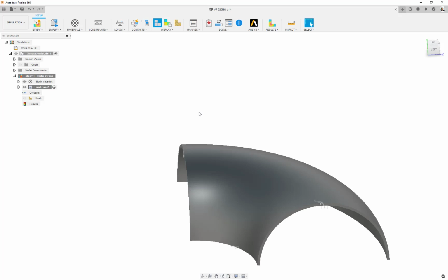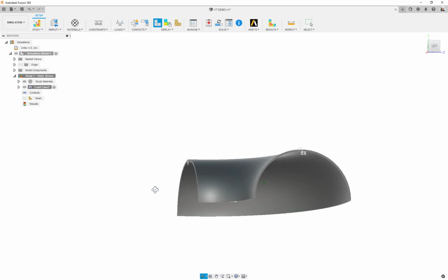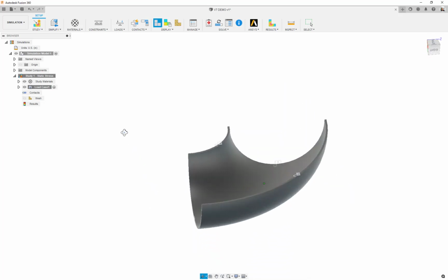And now this model is, because it's a single body, and at different locations on the model, I've accounted for basically all 3 translational degrees of freedom. So it's really kind of a neat thing. I know I keep harping on it, but basically, we're going to apply internal pressure to this, which is going to cause it to expand outward in all directions, but yet the model is still statically stable because of the symmetry constraints that we apply to it. So it's a really neat technique. I'm kind of a fan of it. So anyway, we'll move on from there.